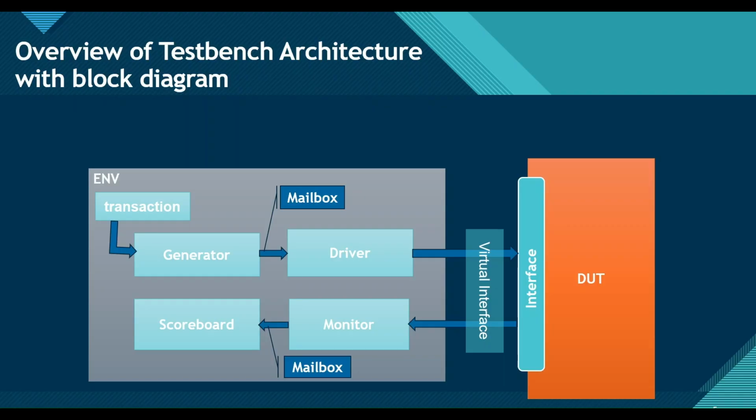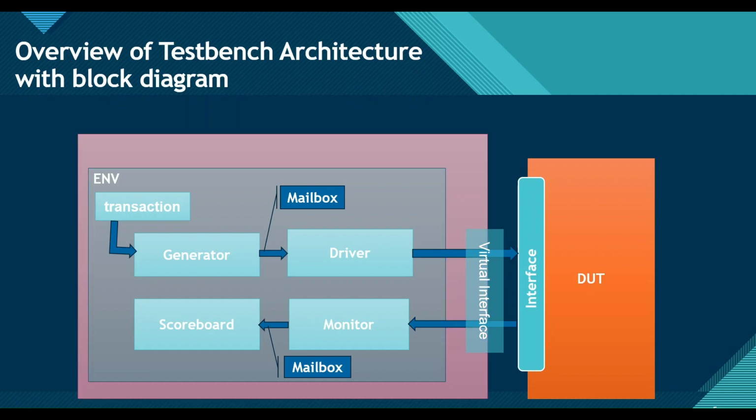Next, we will design the environment class. In this environment class, we bring together all testbench components in one place, and it contains the handles of the generator, driver, monitor, and scoreboard. The details of the environment class I will discuss in further slides. Next, I create the test file, and the test file is used to create the object for the environment class.